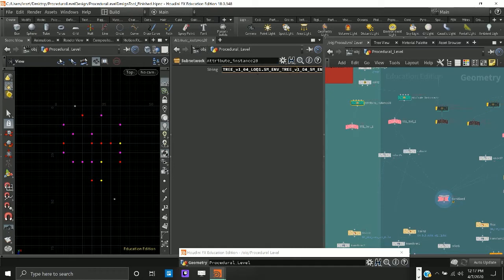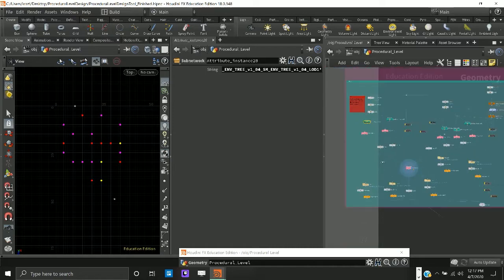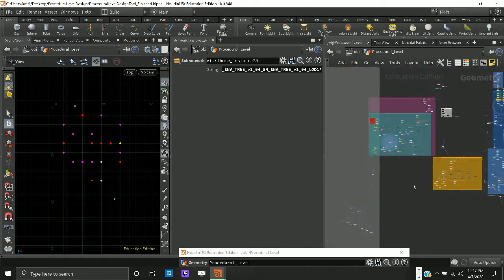And these little bits here are from Unreal, and you go into the engine, and then you want to right click on the mesh that you're wanting to instance here automatically, and paste it into the string. And then when you load up the HDA into Unreal and just kind of throw it into the scene, it generates at its default values, whatever those are set at.